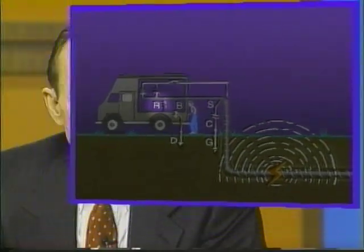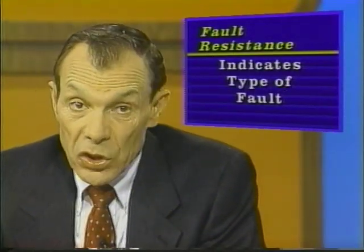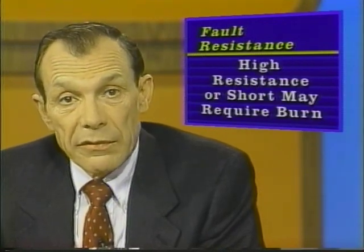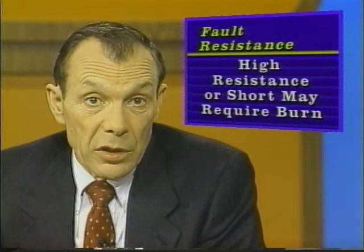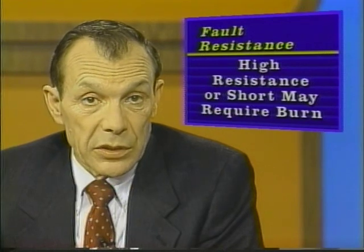Before you connect the thumper to the faulted cable, learn as much about the fault as you can. After isolating the cable at both ends and grounding it for a short period of time, remove the grounds and make a resistance measurement to see what type of fault is present. The more you know about the fault, the easier it will be to make the fault locate. If the fault resistance exceeds 200 ohms, you will have to burn the fault down to 200 ohms or less before a low voltage radar set can be used.